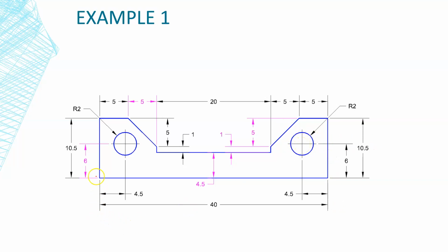Okay, so we can either choose to start at 0,0, or we can start anywhere we want to build the outside and go ahead and manipulate the UCS and place our circles. So on this one, I will start at the 0,0. So you're going to see the X and Y going to be located here.